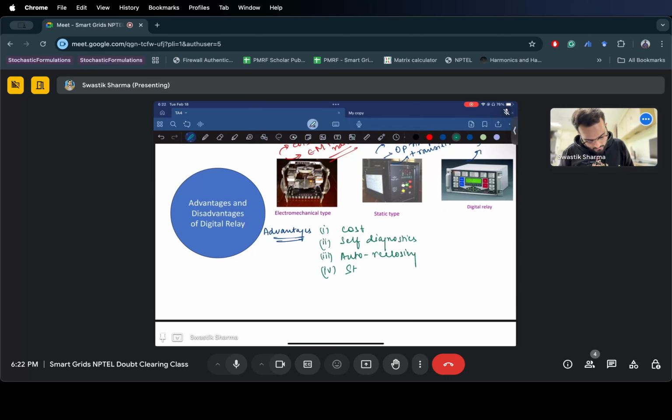Yeah. So they have storage. As we said, these DPRs, digital protective relays, consist of storage where they can store momentarily, or they can also have mass memory where they can store data related to fault, pre-fault, and post-fault conditions, so as to diagnose what really caused the disturbance, what really caused the relay to issue a trip command, and other related parameters.